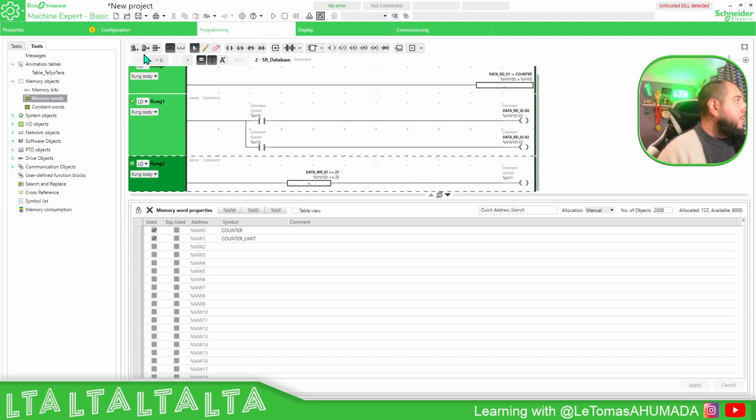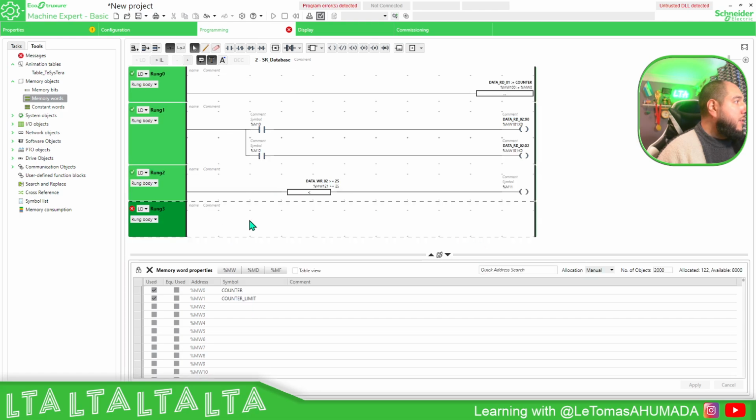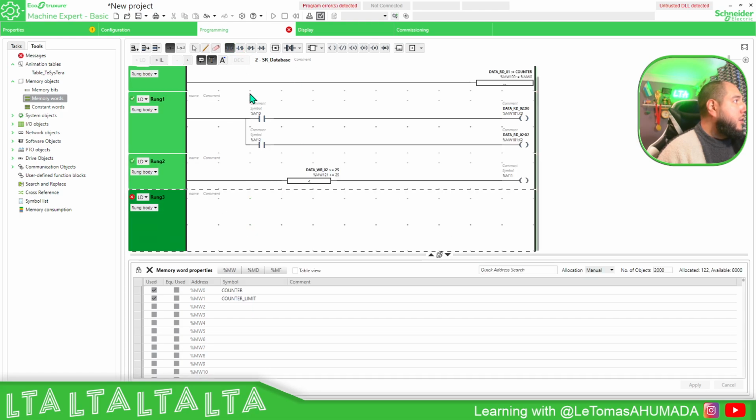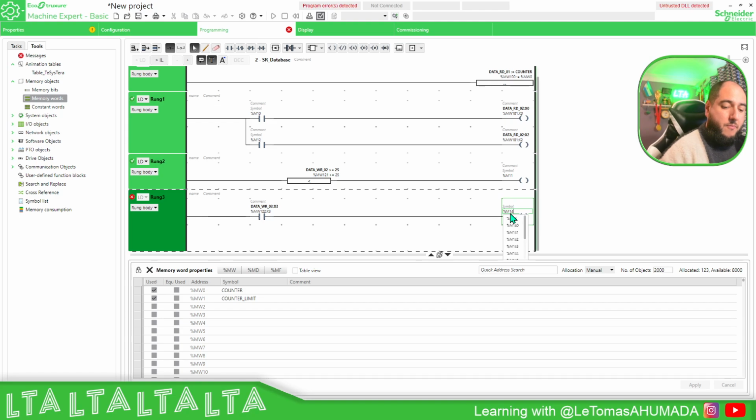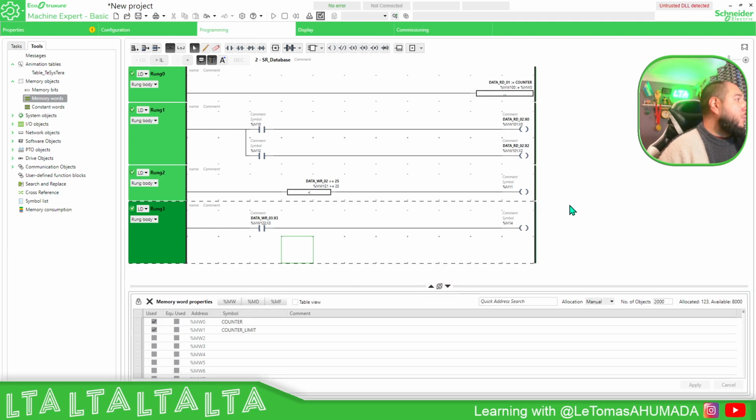If I want to use a Boolean coming from the other side, imagine that it's going to be MW122 colon X3. Then I move this to M14. That's another option, and it will work. Okay, so I have this information. So what I'm going to do now is send this into the M221.